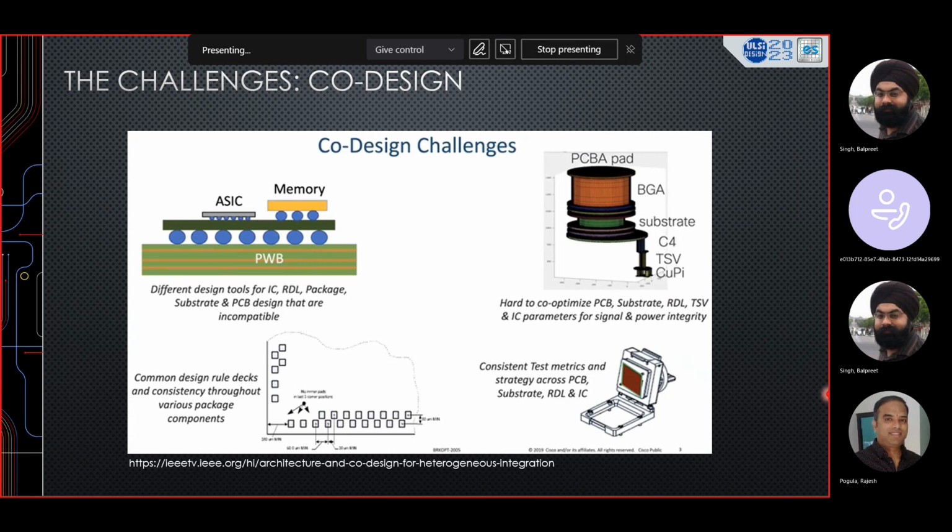And also, how do we co-optimize, let's say we have IO sitting in one place and that connectivity goes through two different dies. As Biswas was showing in one example, IO is in one die, but the connectivity goes all the way through the interposer die, package, PCB, and so on. How do you extract the whole piece and make sure it is still meeting our signal integrity requirements? That's why it's becoming extremely important, but there are challenges as well, is what I'm trying to highlight here.